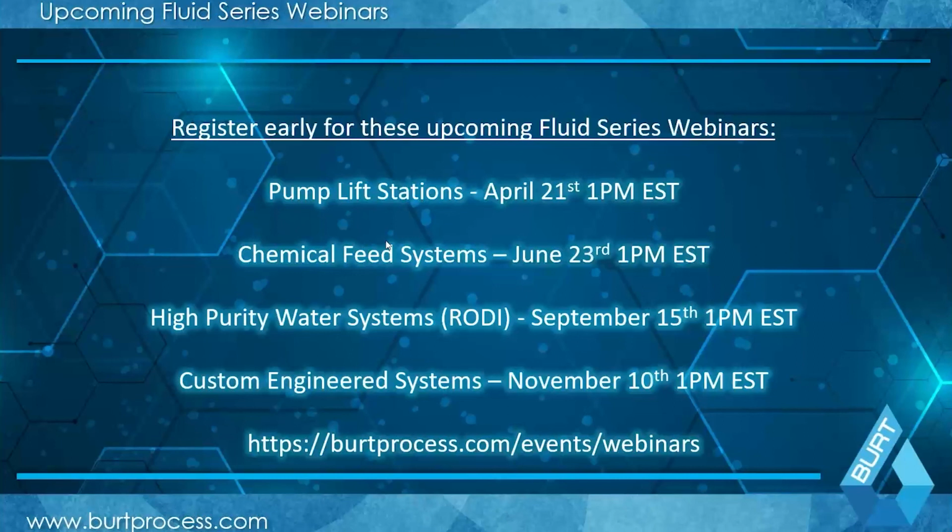Our next question: do we have a preferred type of pump, diaphragm versus peristaltic? By and large, I've generally seen electronic diaphragm metering pumps utilized for pH neutralization systems. I have seen peristaltic used sometimes, but a lot of the metering pumps have a little bit more control that can be utilized with some of the systems. But again, it does depend somewhat on preference.